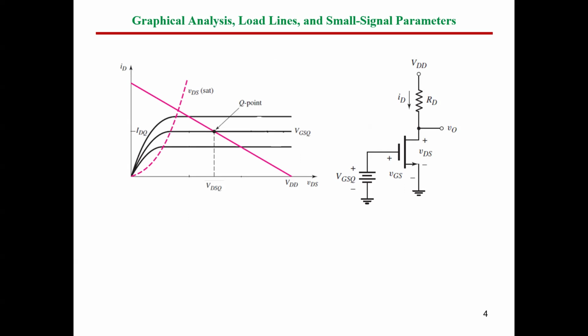You know, guys, this is our MOSFET. This is a simple circuit of a common source MOSFET. The source is connected to ground. The drain is connected to a resistor, then to a DC source. This is the VGS connected to the gate, and this is V drain to source, and we call this V out. Why is this V out? Let's discuss that on our curve here.